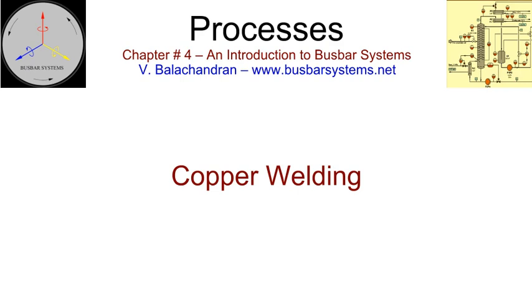For fusion to take place, there must be an adequate weld pool. Preheating will lead to a change in the mechanical properties, especially on cold-worked conductors. Welding of copper is limited to flat and round bars and round tubes. The welding procedures for these are well established and documented. Welding of copper at the site is rare and not recommended.